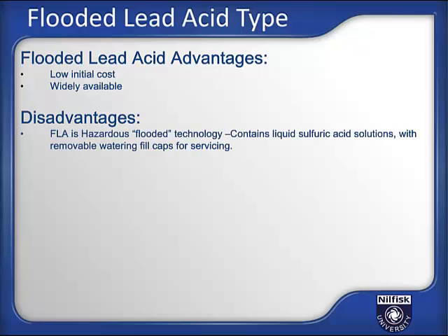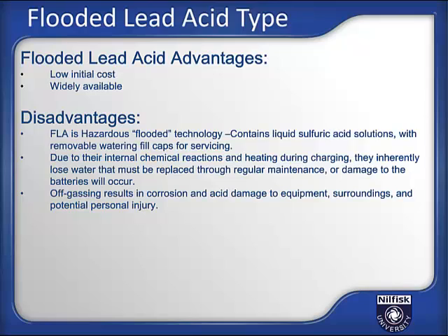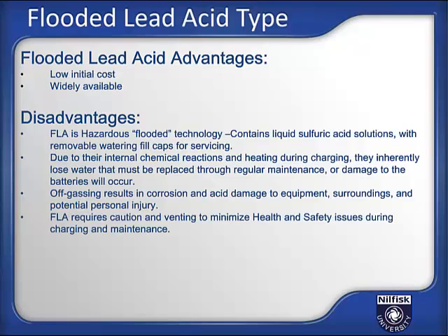Flooded lead acid is hazardous flooded technology. It contains liquid sulfuric acid solutions with removable watering fill caps for servicing. Flooded lead acid, due to their internal chemical reactions and heating during charging, inherently lose water that must be replaced through regular maintenance or damage to the batteries will occur. Flooded lead acid produces off-gassing, which results in corrosion and acid damage to equipment, surroundings, and potential personal injury.